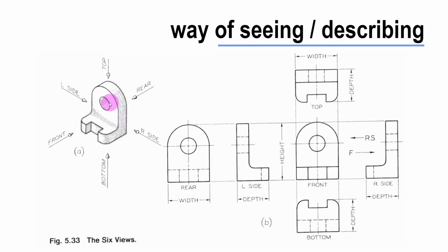So if I'm looking at this object from above, from the top view, this hole that's blasted through this back face isn't visible in the top. If this was made out of a solid piece of wood, I can't see that hole going all the way through, which doesn't mean that it's not there. It just means I can't see it in the top view, which is why it's projected with these hidden lines for the quadrants of it.